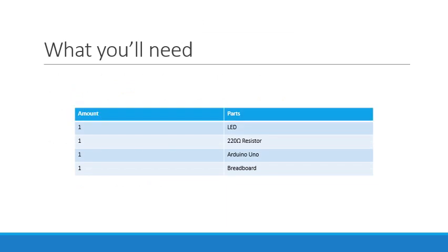The things that you will need for this are your LED, your 220 ohm resistor as a current limiting resistor, an Arduino Uno, and a breadboard.